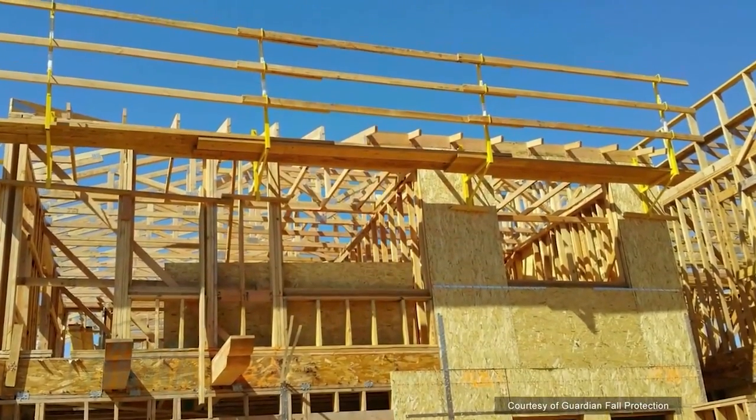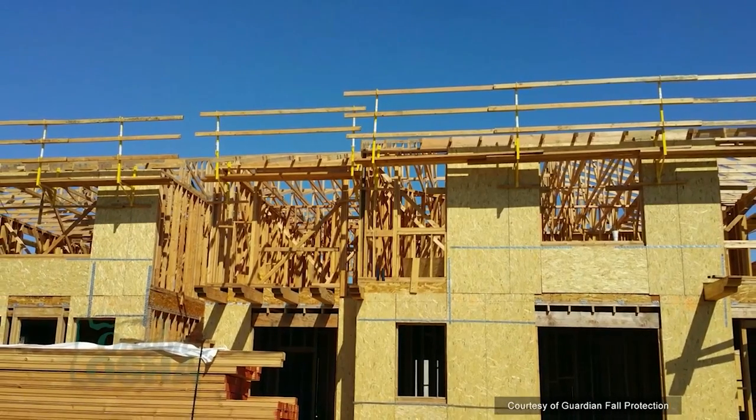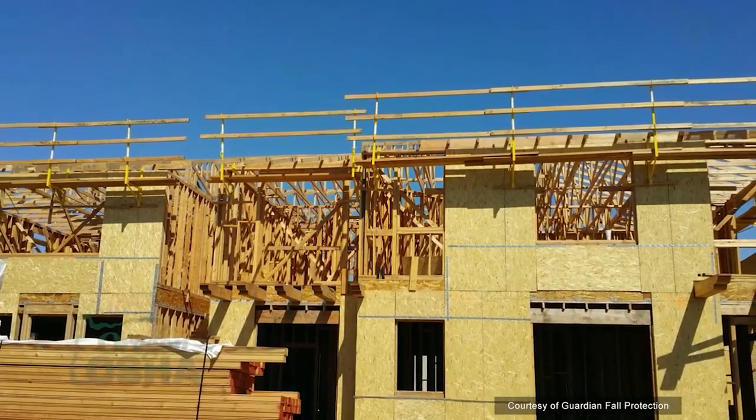One of the other fall protection systems that I've seen mainly framing contractors use is scaffolding, or carpenter scaffolding, where instead of standing on top of the wall plate to, say, set trusses, they're standing on a built-in scaffolding system. It's a couple of feet down from the top of the wall. That way they actually have better leverage with those trusses, and they're not exposed to the fall to the outside of the building. They're in better control, and they don't have that hazard there.